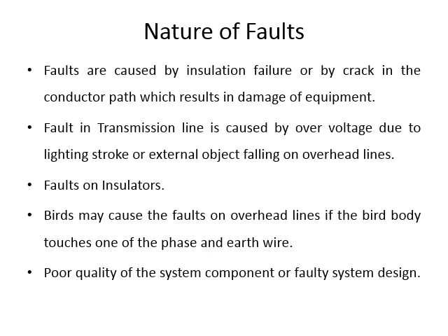In case of cables, transformers, and generators, the causes of fault are the failure of solid insulation due to aging, the heat factor, and the moisture factor. There could be mechanical damage or accidental contact with the earth, flashover due to overvoltage, etc. Sometimes the circuit breaker may trip due to an error in the switching operation or testing or maintenance work.